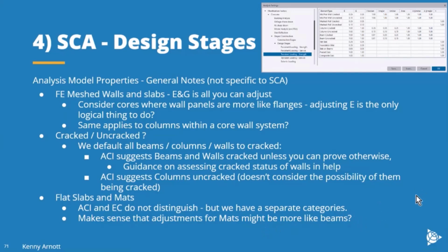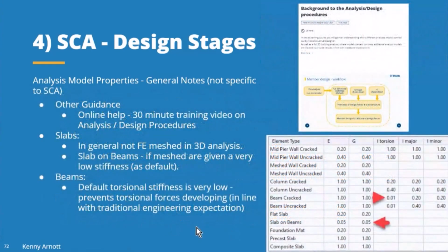So that's why in TSD we've separated them, so you can give them different factors. As you can see here, we've got flat slabs with one factor. Mats potentially have a different factor. It's up to you. In that whole area of analysis model properties, again, I say this is not specific to stage construction analysis. If you're looking for more information about that, in the online help there's a 30-minute training video on the topic. So I think that would be the best place to go to look for more information.